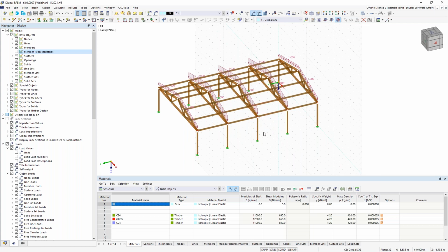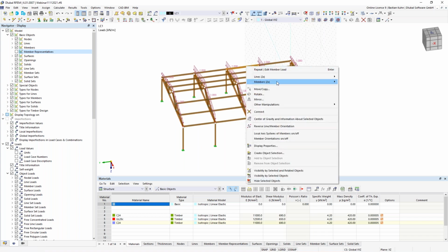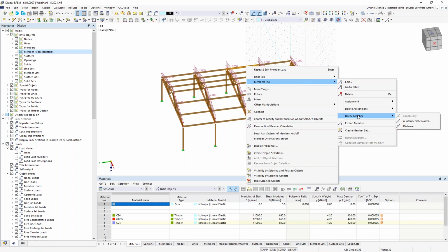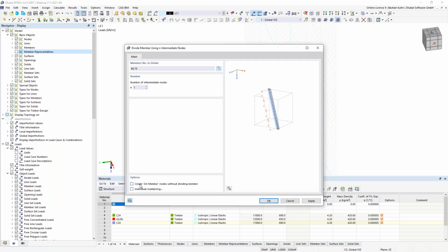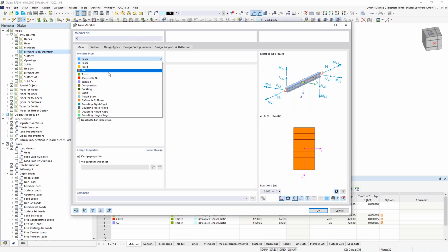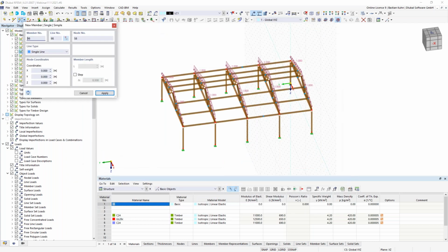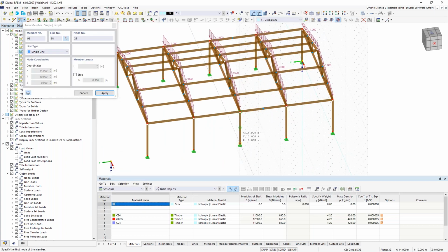And now we need to define there also stiffening elements. I choose to define my stiffening elements near the middle of the structure, because it makes the most sense to me. Once again, divide the member by 1 node and without dividing the member, and define the section there. And I'm once again choosing the truss and the section 14 by 14. Okay, oops, here as well, and here. So now the walls are stiffened out into the Y direction.